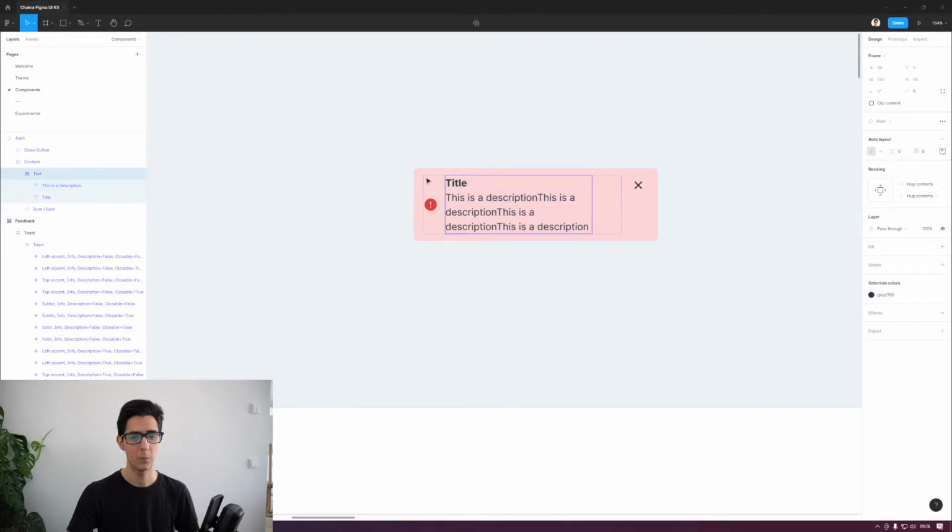So what we eventually want to do is say that this whole auto layout here that you see that says text, it should take up the whole width of its parent container. In this case, that is content. So because content is working well, right? It says fill container, and that's pretty good. So the problem that we have is with this one right here. So you would naturally come and say, okay, I want this to be fill container. So that works nicely. But now we still have an issue with these layers here.